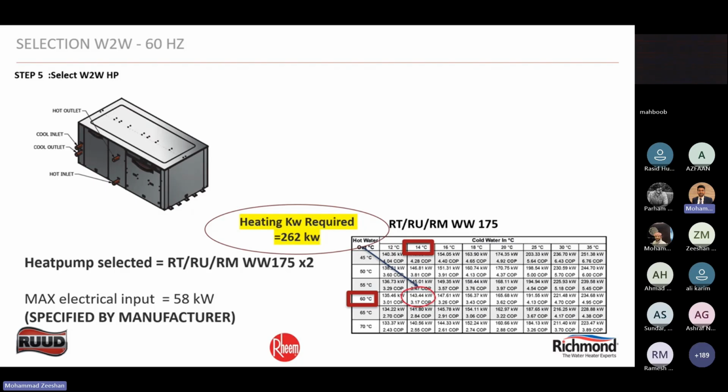During the summer, the flow is directed from the chilled water line to the heat pump, and that will operate. During winter, you use it the other way around, where you use the tanks to cool and take that energy for the heat pumps to heat the water on the other side.